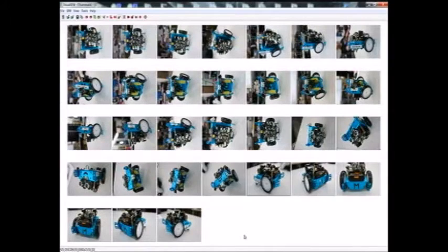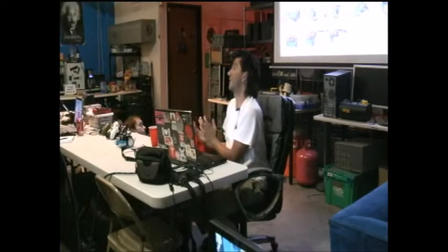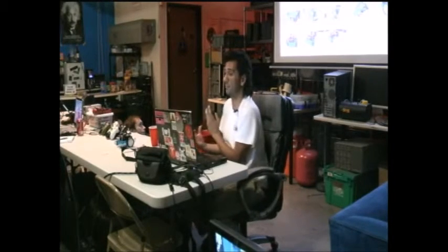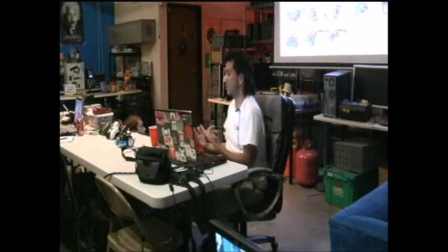And you also have to take some considerations about reflective surfaces or surfaces with any bit of specularity, like a half gloss, a semi-gloss metal surface. If it's reflecting any points of light, that distorts the result of the scan, but it doesn't ruin the scan. This is actually a really robust method of reconstruction.